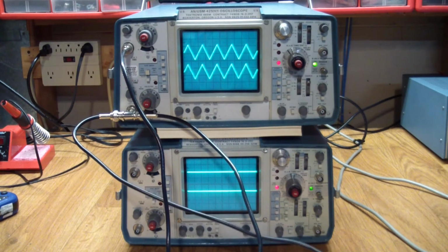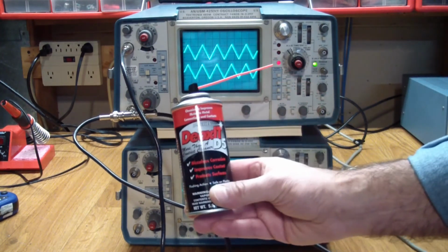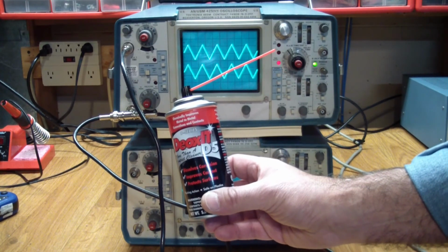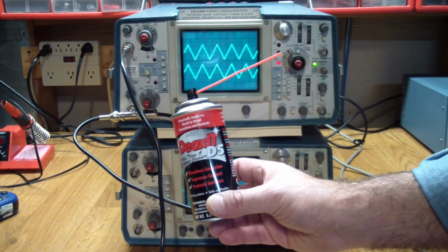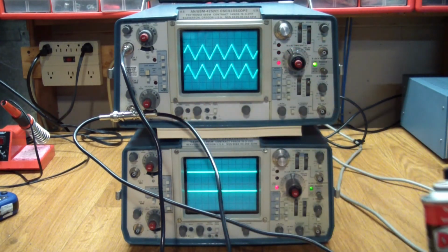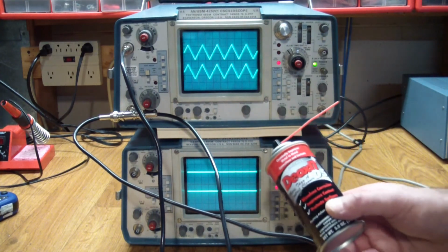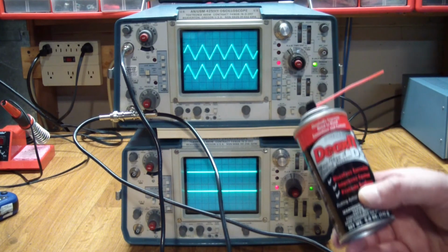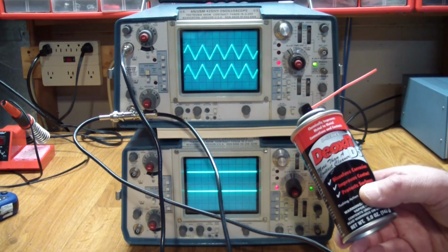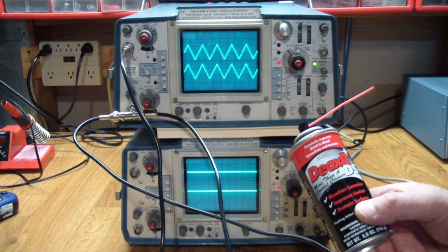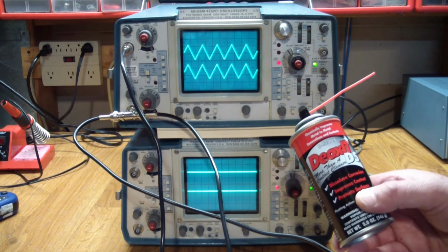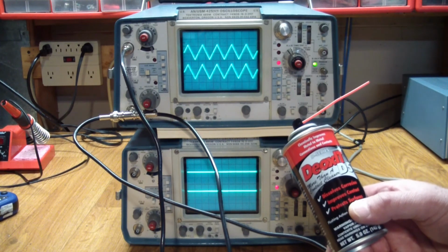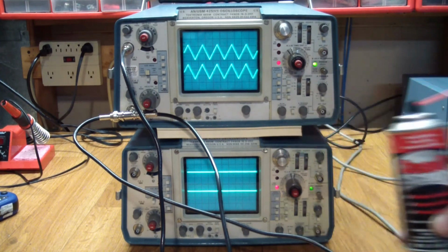And second of all, the contact cleaner I use is Deoxit, which I think is available more widely than just in the United States. But quite frankly, for this application, for sealed pots and for the contacts, if there's no corrosion and stuff on them and they're just a little bit dirty from use, I think your plain contact cleaner that you can buy at your electronic supply store, or alcohol for that matter, high percentage IPA, will do the same job.